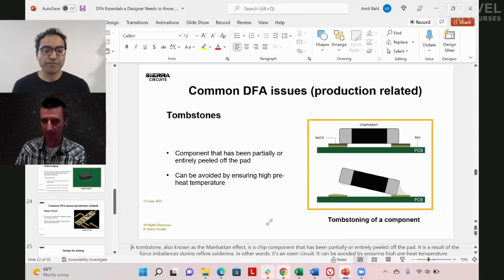Oh, okay. So it's not only about the design, but also about tweaking the manufacturing or assembly process. So, for example, in our facility, because we're high mix, we'll have one design that has heavy copper, and then we'll have another design that's tight pitch. Whereas if I'm a cell phone manufacturer, everything I manufacture is low copper and tight pitch. So there's no variation, it's all the same. Now, if everything's coming in the same, then I can tweak my manufacturing operations to be the best for that design. So if you ask a cell phone manufacturer to all of a sudden manufacture power boards with heavy copper, they won't be able to do it, or they'll do a very bad job.